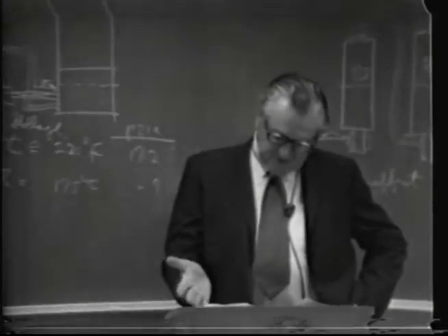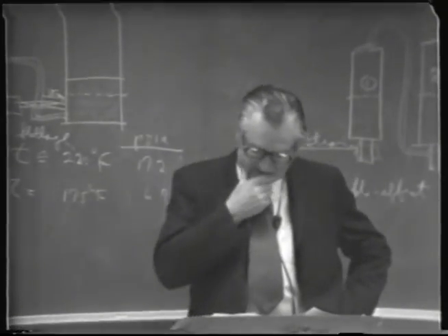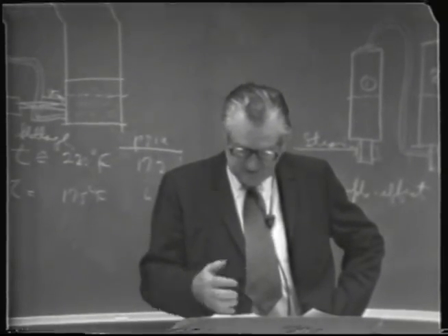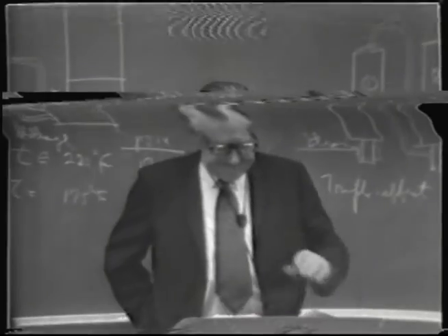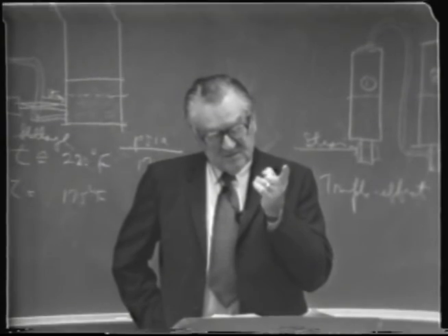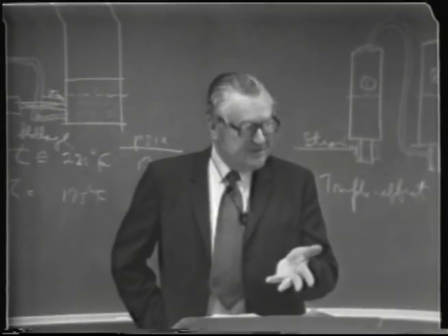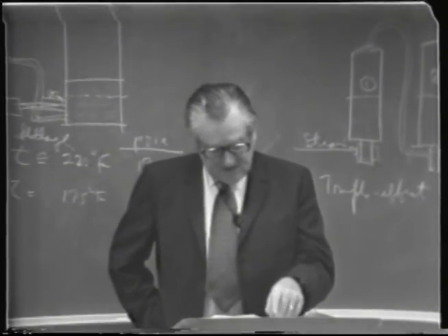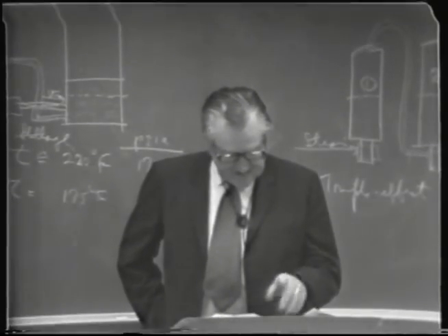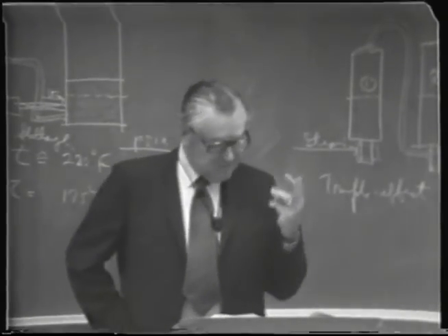where the primary product could be drawn off as a side stream, and the light heads taken and recycled back perhaps into the purifying column, not shown here on the drawing, and a conventional bottoms product taken out. This is a fairly good design from the standpoint of removing aldehydes, because aldehydes are more effectively removed from dilute alcohol solutions or from water than from high concentration of alcohol. So the disadvantage of this is that all three columns require their own heat supply. You have to supply steam to all three columns.